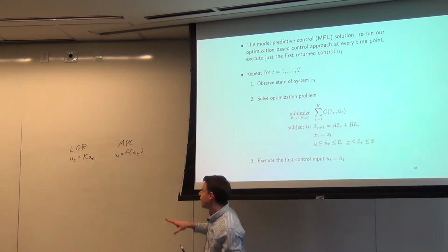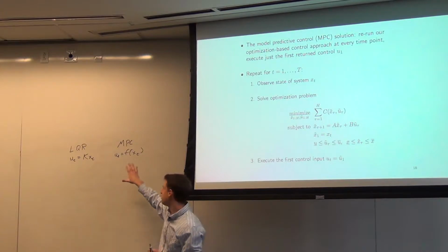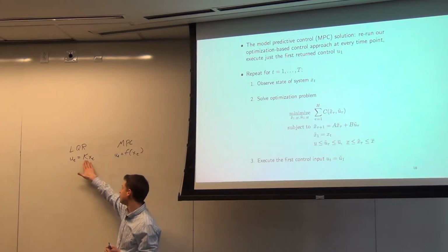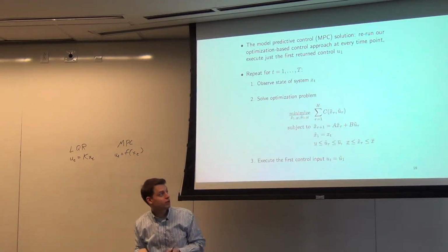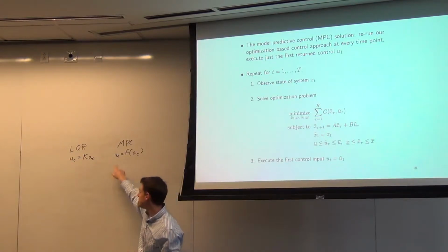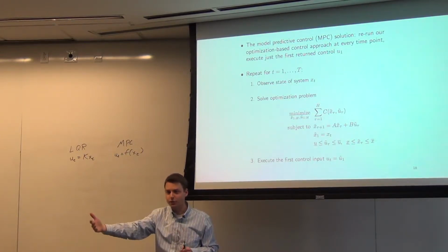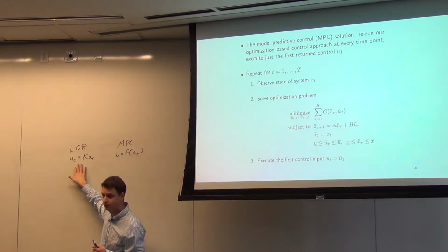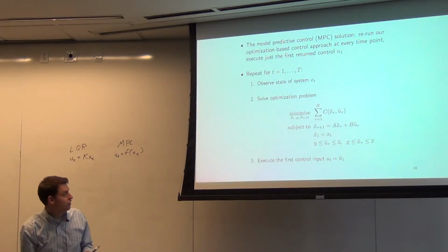Right? So in both cases, we have sort of a controller that uses the current state to determine what the next action should be. It's just that this one involves an optimization problem, this one involves a matrix multiplication. So you can also imagine which one is simpler, right? It's a lot faster to multiply by a matrix than it is to solve a brand new optimization problem. Especially if you have to control these things hundreds of times per second. This could be pretty tough to do. Whereas this might work better. On the other hand, if you have lots of time between steps, like you're controlling over days how you're going to allocate power, you can nicely directly incorporate constraints into this one where you can't do that with this one. So that hopefully sort of demonstrates a little bit of the benefits and costs of each of these.